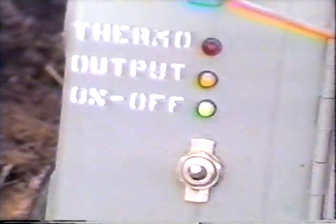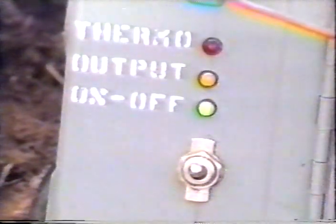During the first few minutes, the lights on the controller should be watched. Green indicates the unit is operating properly. Yellow means that the unit is in its heating mode. But flashing red means there's a problem with the thermocouple.